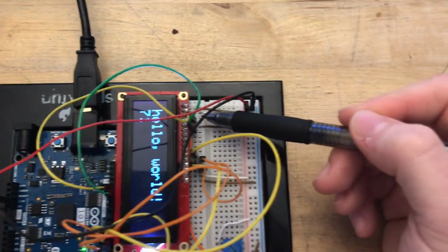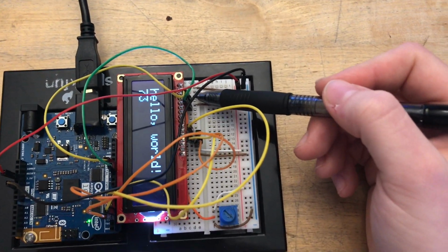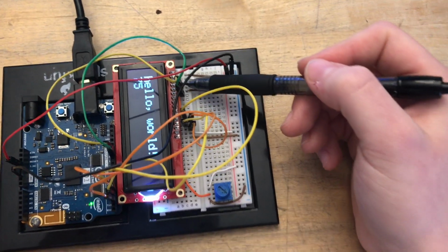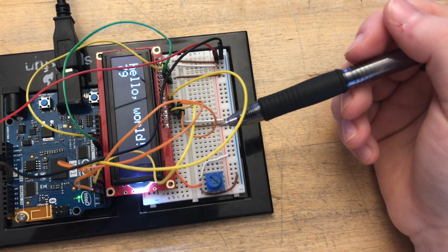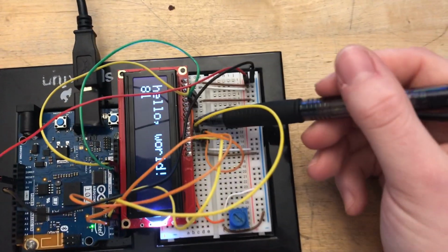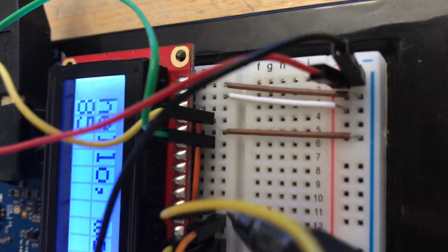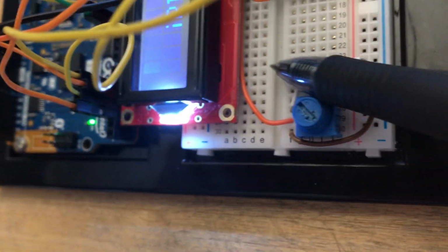Then we're going to go to the next, which is the third pin, and the symbol for that is V0, the LCD operation voltage pin, and that's connected through this orange wire, which is kind of hard to see, this orange wire here, and that's connected to this potentiometer down here. We'll get to that in a bit.